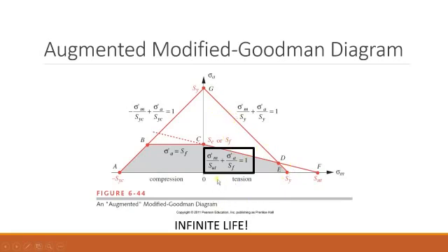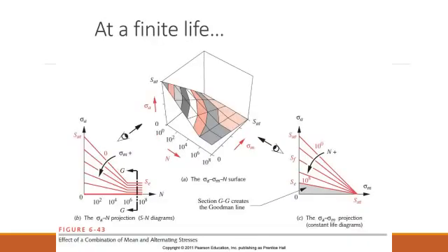This one shows either infinite life, or if we're talking about the fatigue strength, then we can talk about it as being 5 times 10 to the 8th, or wherever the fatigue data is given. Let's take a look at a 3D image of these two graphs projected onto each other. As you can see, as I look this direction, I see number of cycles on the x-axis and the alternating stress on the y-axis. That is our SN diagram for only alternating stress at this end.